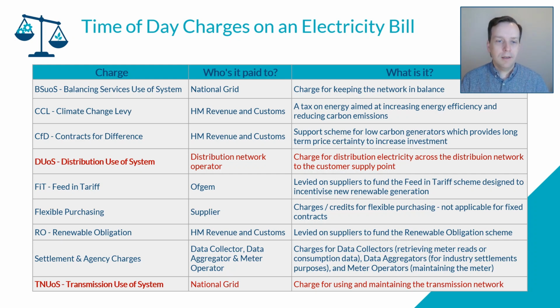So here in the UK we have at least 9 individual charges or penalties based on the kilowatt hours used, but also on your connected capacity. Somebody with a connected capacity of 1000 kVA, kilovolt amps, would be charged more than somebody with a connected capacity of 500 kVA.